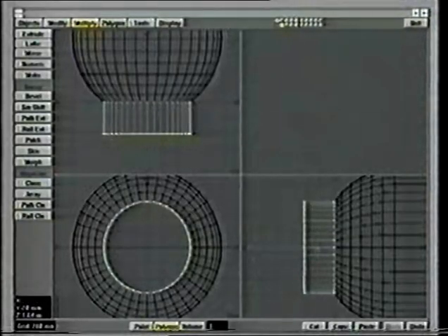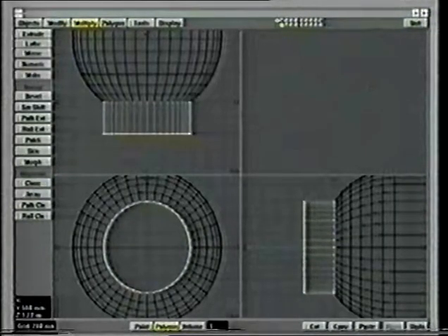Okay, there's a nice edge there. Now, this might not seem like much of a bevel to put on it, but what happens is when the light catches that edge, you will get a highlight on it. You'll get a specular highlight if it has any specularity in its surface. Whereas if that were just a square edge, because the computer doesn't have the sort of infinitesimal rounding that real-world organic things have, it won't give you any kind of specular highlight on that.